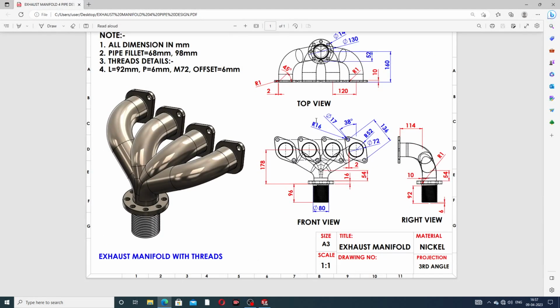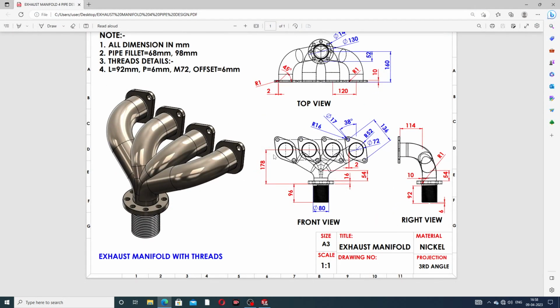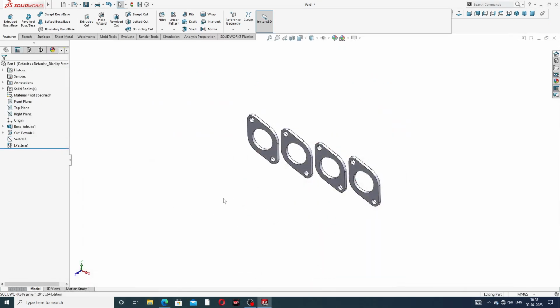And next, this circle is drawing here, and this circle is a pattern also used here, and this circle is big, diameter is 130 millimeter, and this center to distance is 160 millimeter, drawing here. And one point is very important. This point is 178 millimeter. This direction is upward. This is a downward direction. This is perfect.